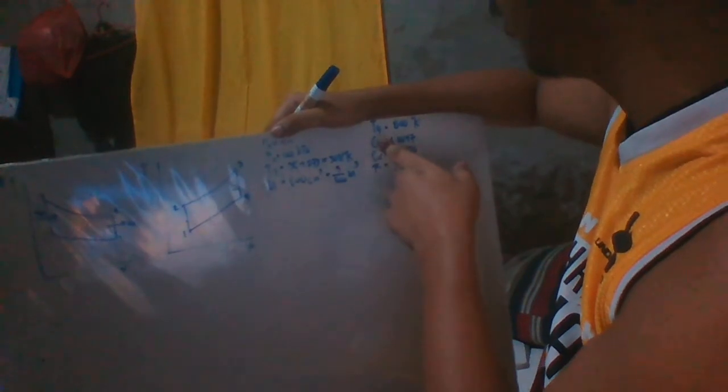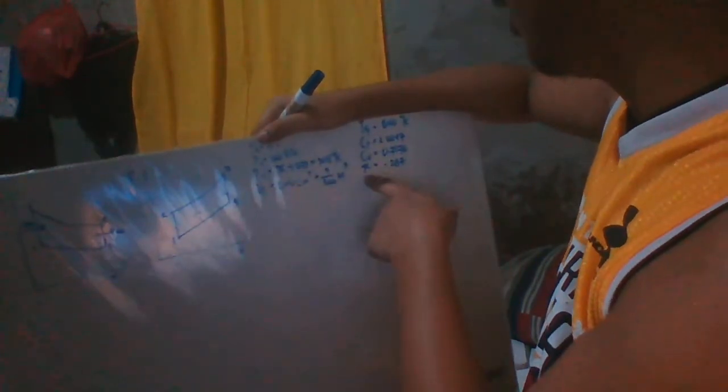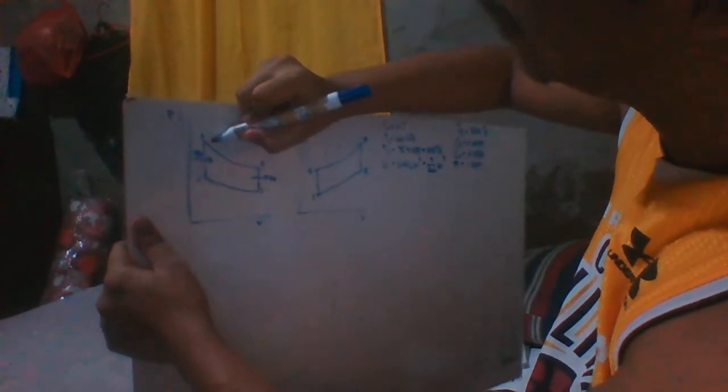Specific heat at constant volume, Cv, is equal to 0.7176 kilojoule per kilogram Kelvin, and R is 0.287 kilojoule per kilogram Kelvin, at room temperature, so we will make these our constants. In the problem, we will look for the highest temperature and the highest pressure, so it means pressure 3, P3, and highest temperature, T3.